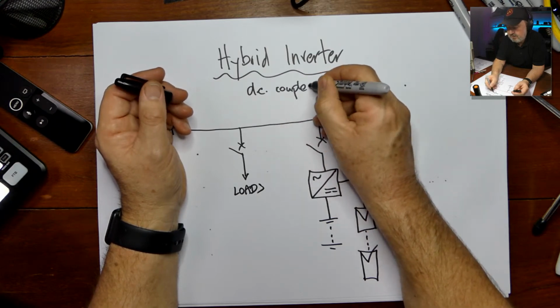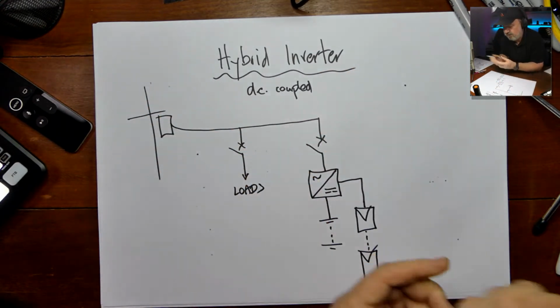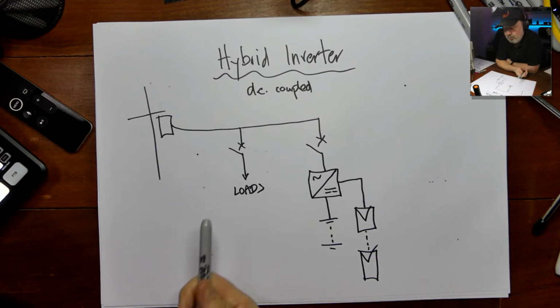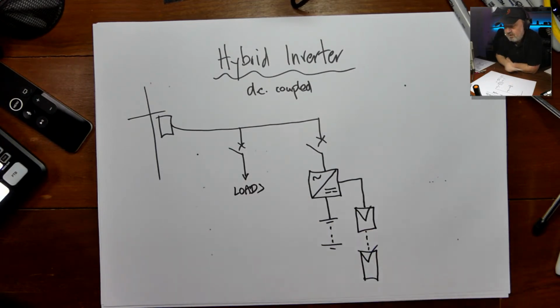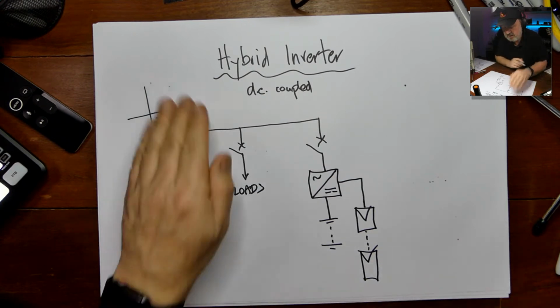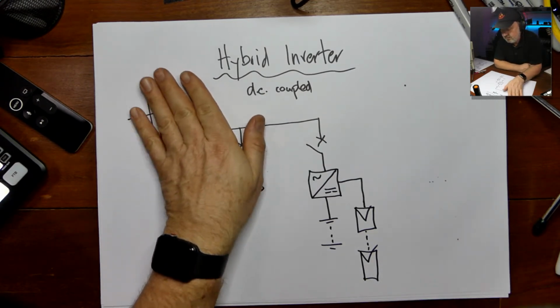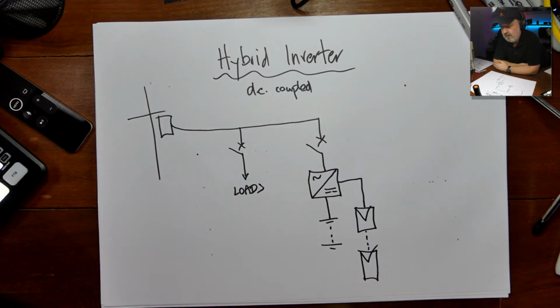Another side benefit of DC coupling, whether it's the off-grid style with the separate MPPT or the on-grid hybrid style, is that it's a dedicated way of charging those batteries. You can charge those batteries even when the grid's not present. It will look after that battery system independently of any grid source.